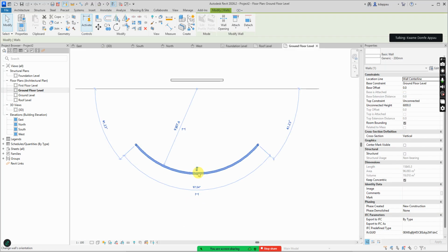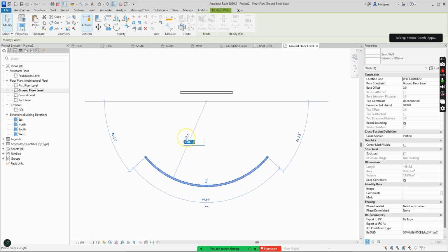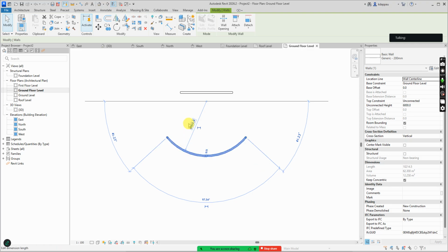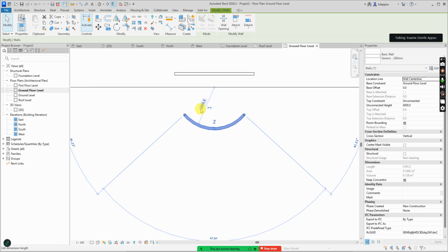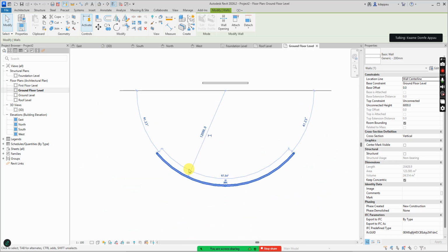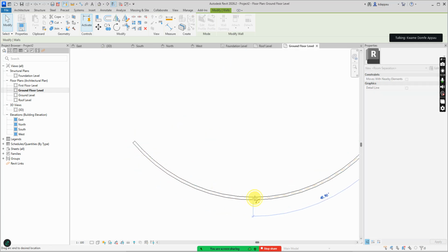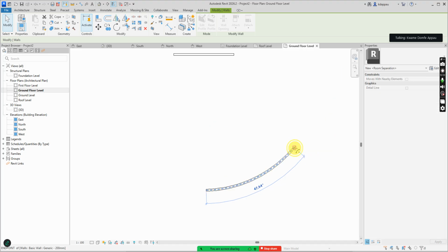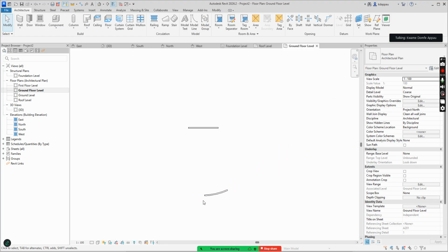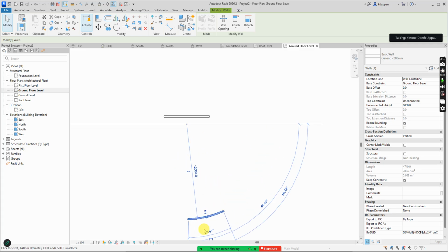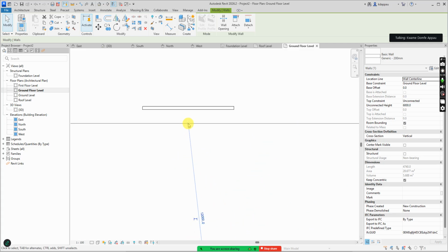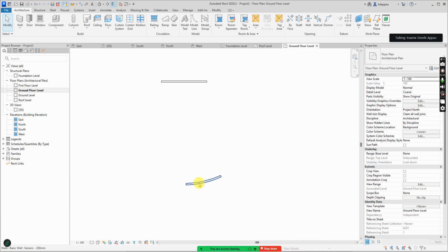If it is a curved wall, you can specify the radius of the curve to be 6,000, or the radius can be 3,000, or the radius can be 12,000. You can specify where it is starting, and you can specify where it is what? Ending. You must know where you want the origin of the curve to be. You have to specify.